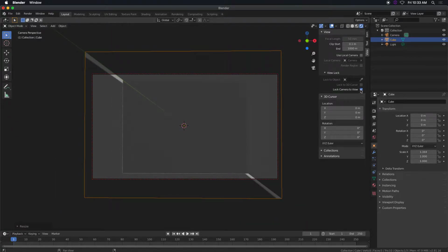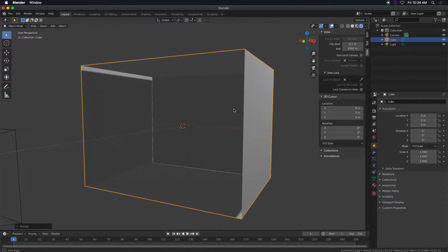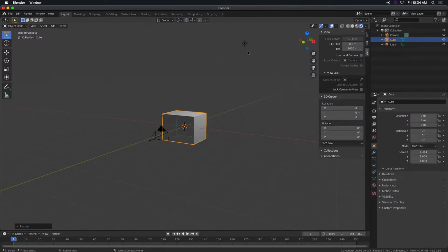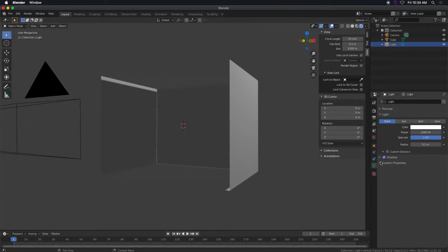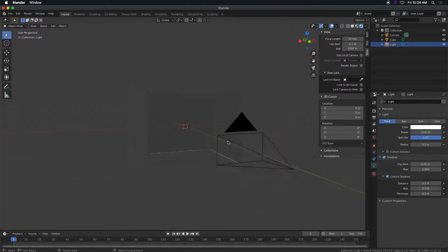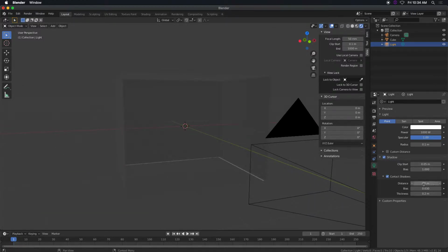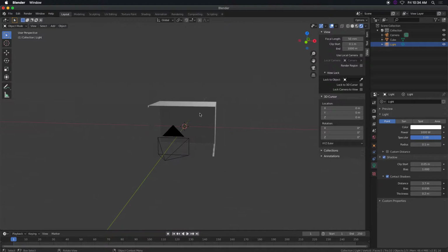All right, let me turn off that. Because we're using this light source here, and if you look at the shadow parameter, contact shadows is not on. So you need to enable that contact shadow. Once you do that, it becomes a little more realistic. It still has issues because you have to go to draw distance and whatnot. You see it? Kind of. All right, we're not using this light here, so we're going to turn that off.